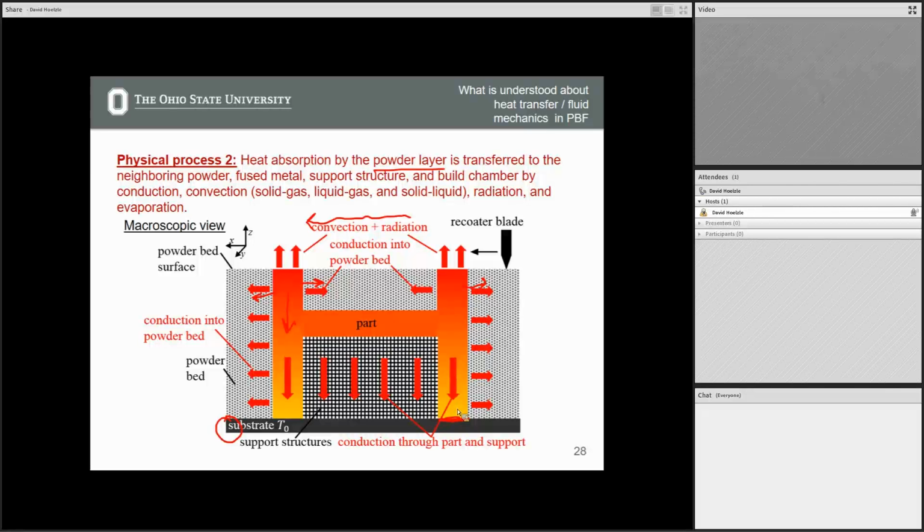So if you ever want to machine something and you have to have essentially no stress on the part while you're cutting it, you use EDM. And you want to have very high accuracy, use EDM as well. Other types of cutting processes have a considerable amount of stress you impart into the part. So, as you imagine, much more expensive than a bandsaw.